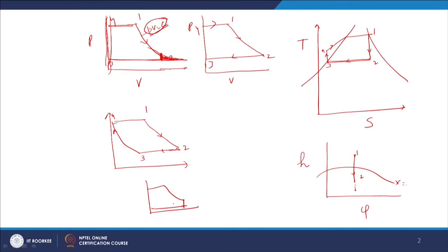But in the steam turbine we can keep on expanding because it is a rotary machine. We can keep on expanding up to absolute vacuum, or absolute pressure 0. But that we normally do not do. Even we restrict this pressure to a certain value in turbines.